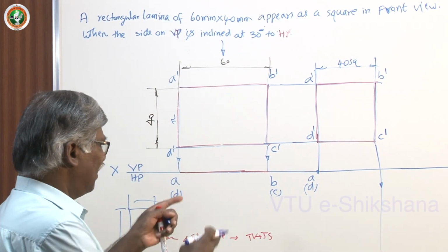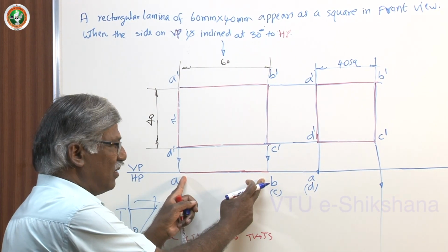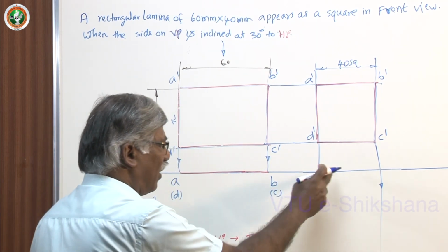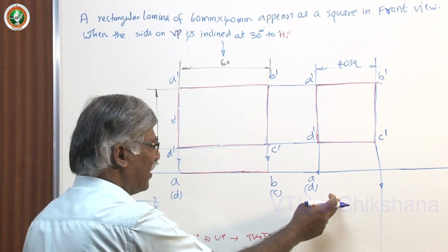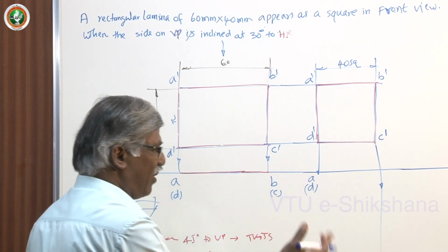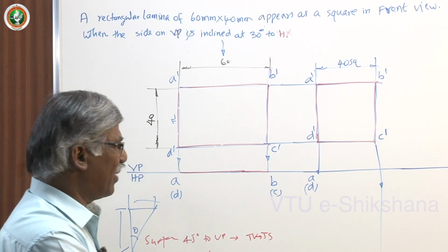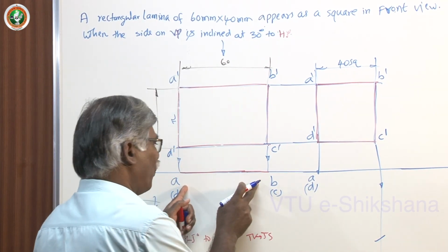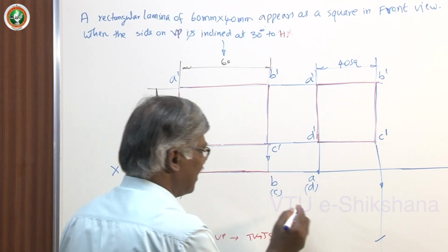Next, take this distance and draw an arc. If we get an angle, we draw a line at 40 degree, 50 degree, whatever is given, 30 degree, then take this distance and draw. Same information we are providing here. Draw an arc with the top view length equal to the radius, that is exactly 60 here.